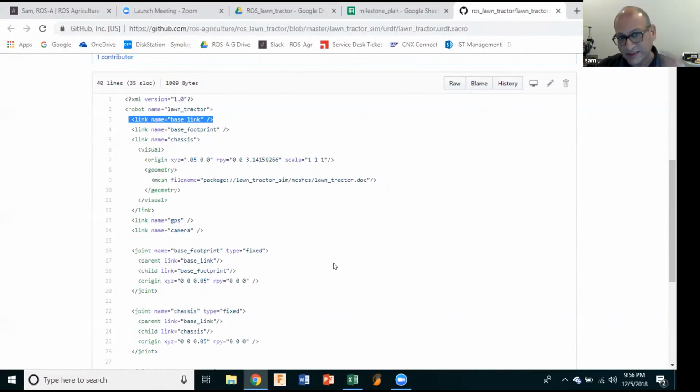So in this case, we have to add the dimension to it. For the base link, we don't want to define that as a virtual link, which has nothing in it. You want to have the geometry, like adding the visual elements to it. You can have maybe only one virtual link, which has no geometry. That should be fine. And that's what I'm talking about.